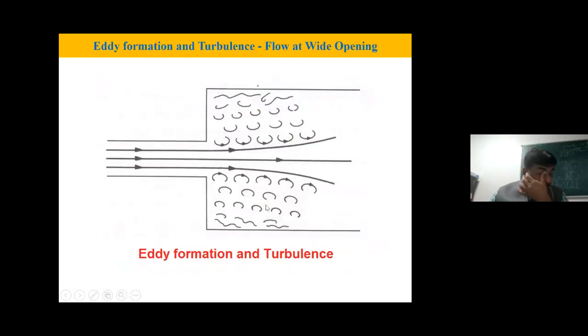What happens inside these ducts if the duct suddenly changes? You can see this is the shape of the duct. Flue gas is coming here, and on the sides these are all the vortex zones, dead zones, where the dust particle deposition takes place.